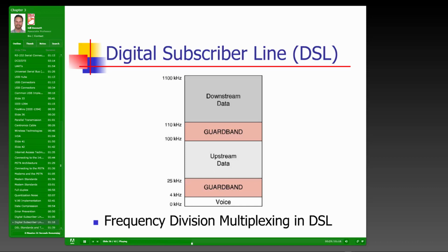Then there's an area of the frequency band that's dedicated to the upstream data. That's you sending information out to your ISP. And then another guard band from 100 to 110 kilohertz. And then at the very top, from 110 kilohertz all the way up to 1.1 megahertz, I should say, 1100 kilohertz, is the downstream, meaning the data that's coming down into your network.